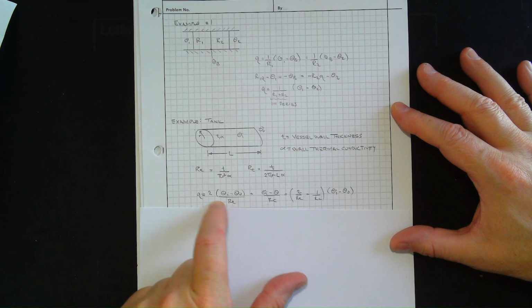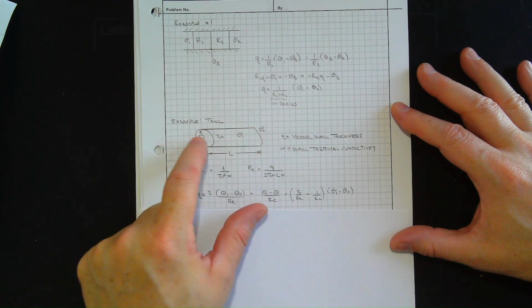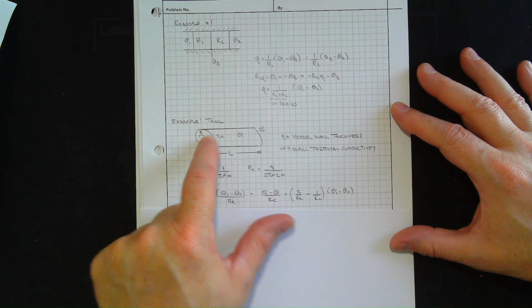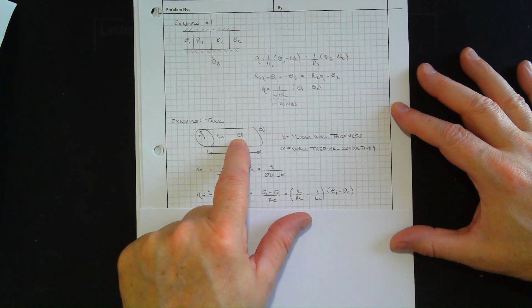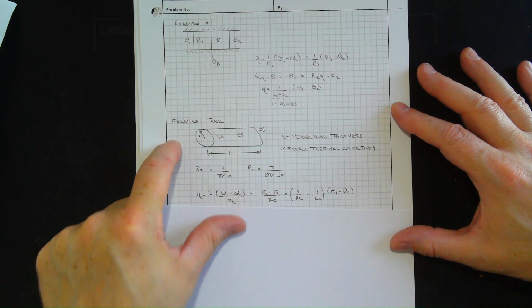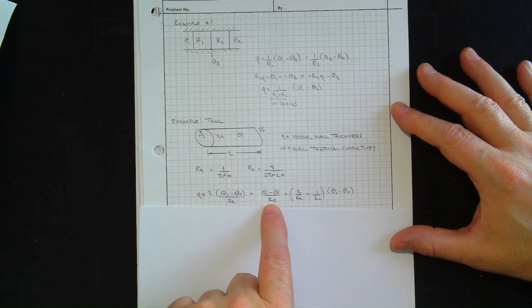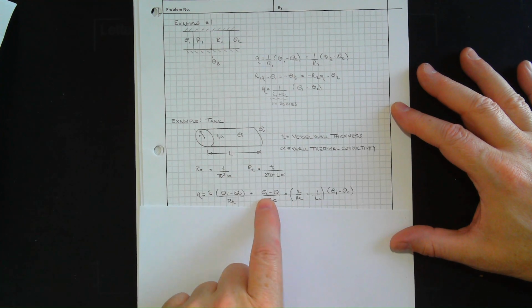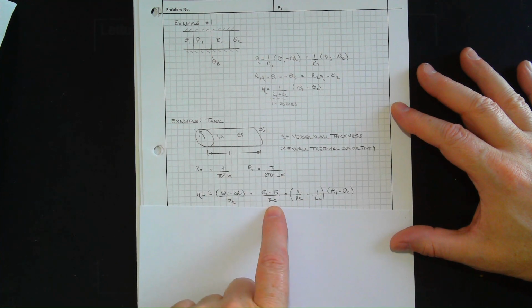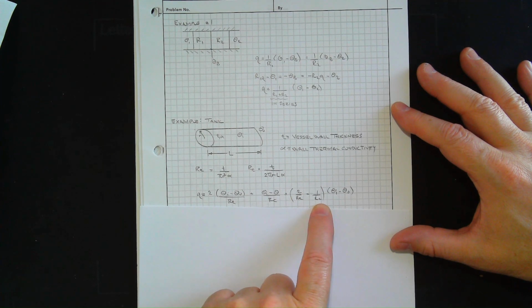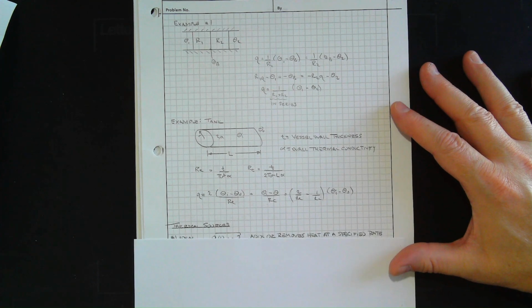Note, these are not in series. This end spans the temperature inside the tank to the temperature outside. That's why we multiply here by 2. And then we'd have simply the walls, which I called RC, theta I minus theta 0 divided by RC. And so we just factor them out, and there they are.